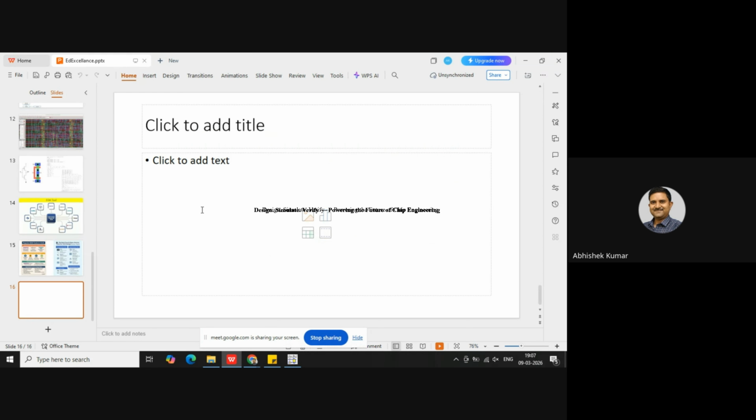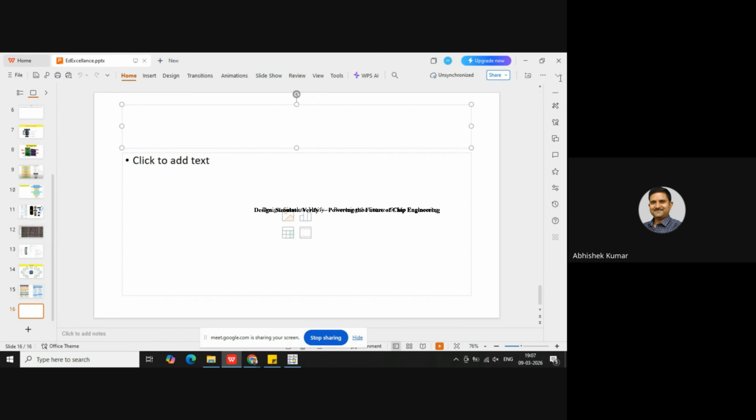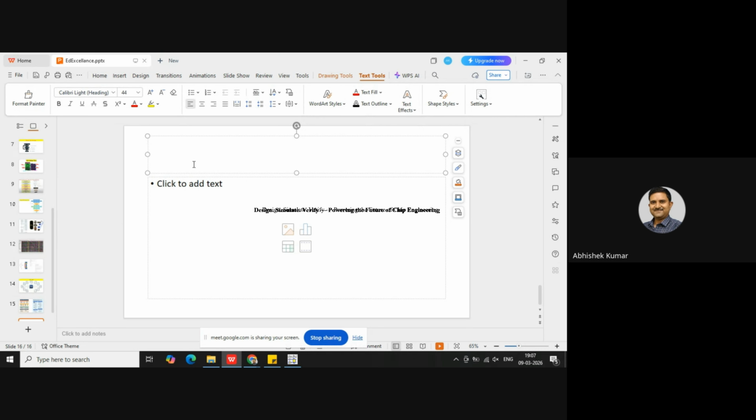Now the question is: implement this equation, 1247, with the help of a multiplexer. Suppose I write S equal to sum of min terms 1, 2, 4, and 7. These are the four terms we would like to implement via a mux. So now, how to do that?